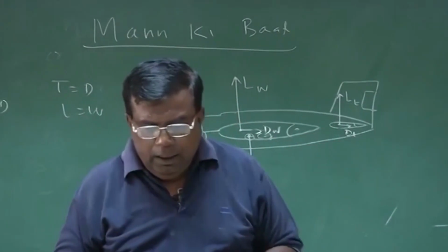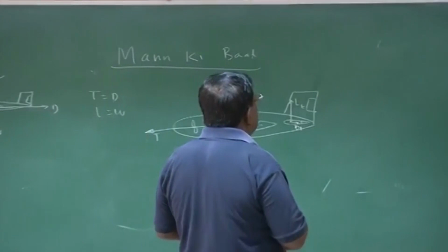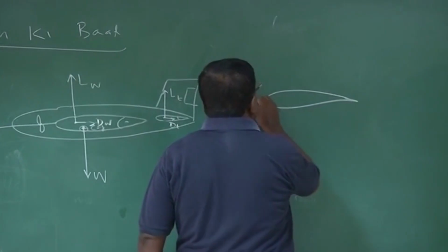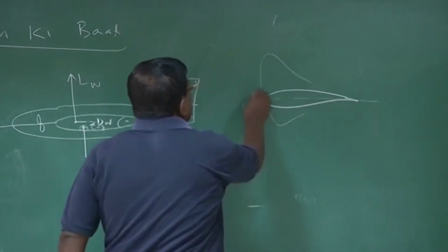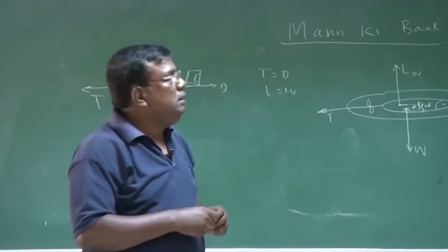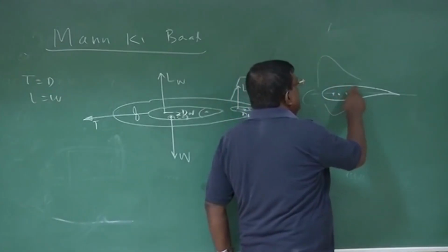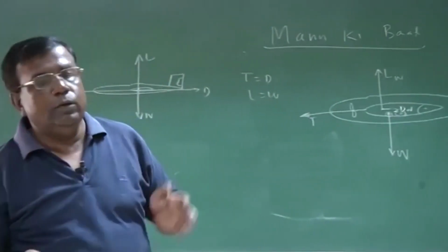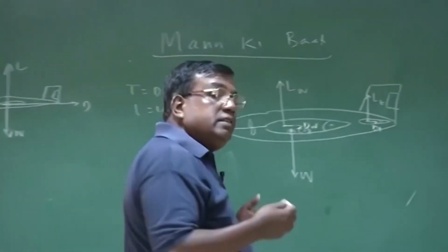In a quick and short explanation, or more of information, let us see this aerofoil, a general aerofoil. Because of the pressure differences, you know, there is a lift. Okay? And we try to talk in terms of CL. And if you take different points, this net force will generate different types of moment, isn't it? Nose up, nose down, whatever it is, depending upon where is the resultant and where is the CG.